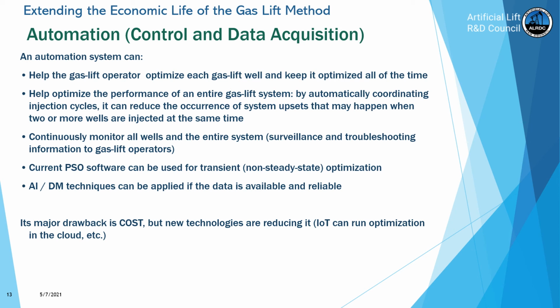And now we have production system optimization software. We have GAP, which is capable of analyzing transient or non-steady state situations. If we have the data and we want to explore the impact that a very strong well producing on intermittent gas lift will have on the high pressure side or the low pressure side of the system, we can do that now, but we have to have the data for that.